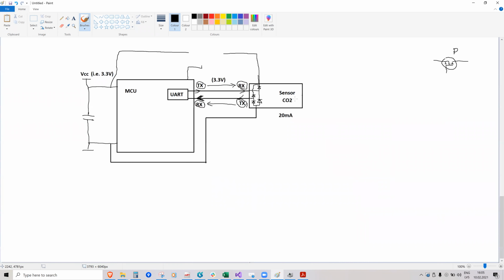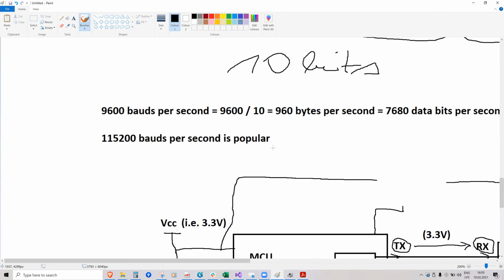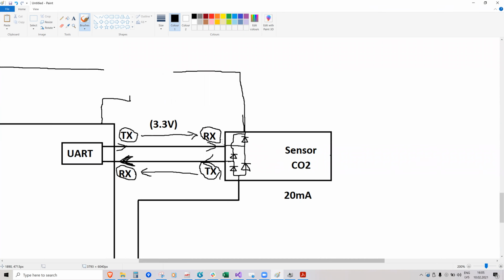As a result, even if you have disconnected the power supply, the UART TX line is high. So here is 3.3 volts, the chip power supply is 0 volts, and the current flows from the TX line through this protection diode to the chip's voltage supply, and internally actually supplies the sensor with power even when you have disconnected its main power supply.